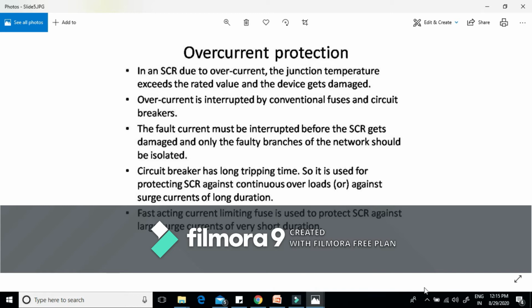The protection against such overcurrent depends on whether our supply system is weak or stiff. In a weak supply system, this high current is limited by source impedance, while in the case of machine tools and excavators, source as well as motor impedance is used to limit this high value of current.